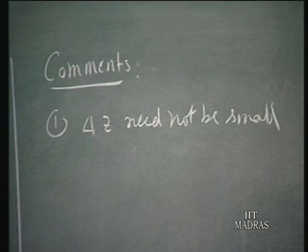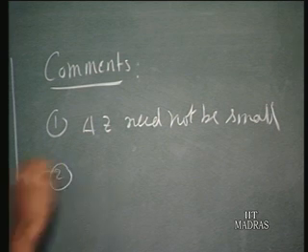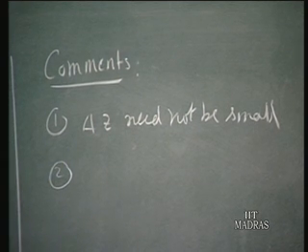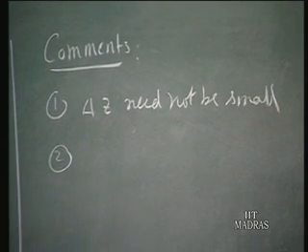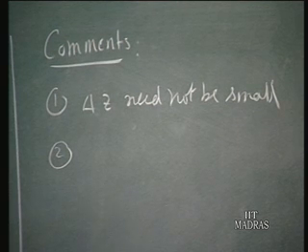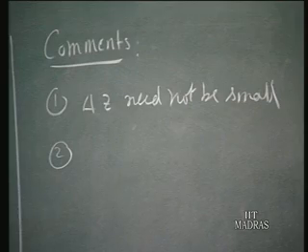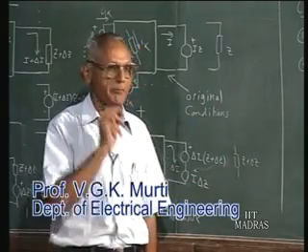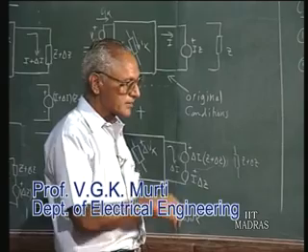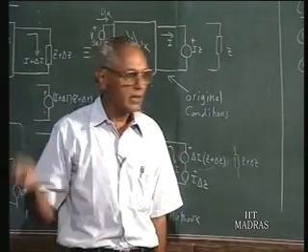Now secondly, if you compare this statement of the theorem with Thevenin's theorem, if you replace the original network by Thevenin's theorem and then change the Z from Z to Z plus delta Z, you can calculate the increments that are produced in the load impedance only. Whereas here you find out the changes in all the elements.